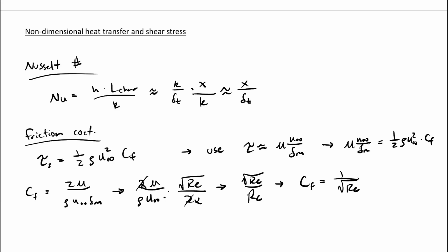So using our conceptual definition of tau, we can say that the coefficient of friction is related to flow that way. One last thought before we wrap up: what's the exact solution? CF, I should make this approximate up here. CF is exactly equal to 0.664 divided by the square root of Reynolds number, right? Does that look familiar from fluids? Laminar flow over an external plate. That's our exact solution. So we're pretty close in terms of our definition, just off by a little scaling factor.